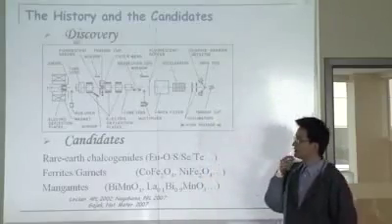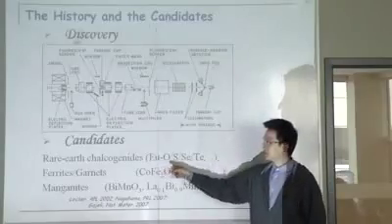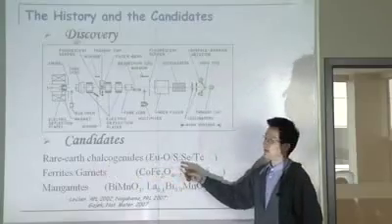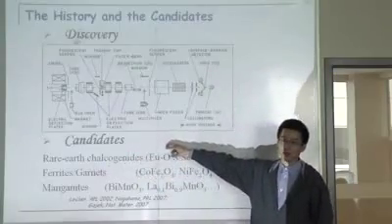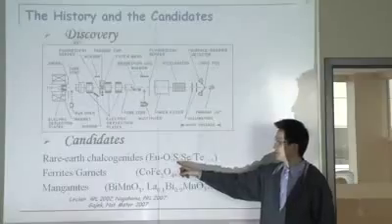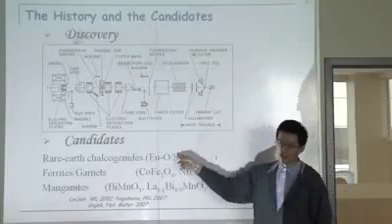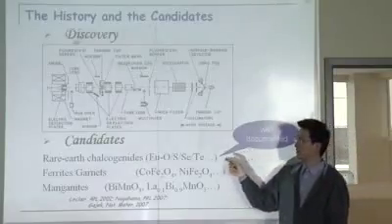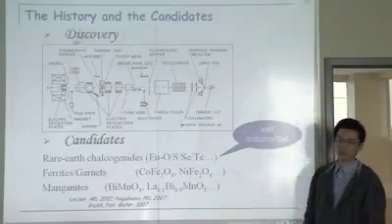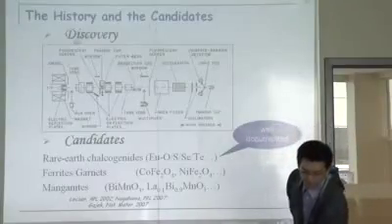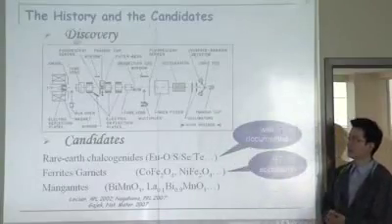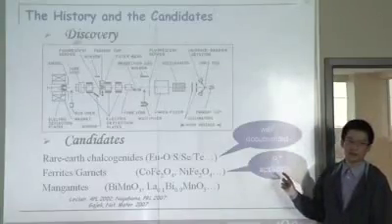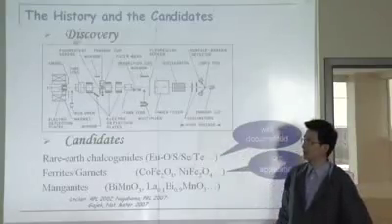And the best candidate for spin filter and the most documented one are the elements based on rare earth and chalcogenide. Chalcogenide means the column below oxygen, like europium oxide, sulfide, selenide, telluride. So these kinds of materials are very well documented in the literature. The spin polarization is well above 98% using this material. The ferrite and the garnet material are the best candidate for the system to start working at room temperature. These are still low temperature operations.